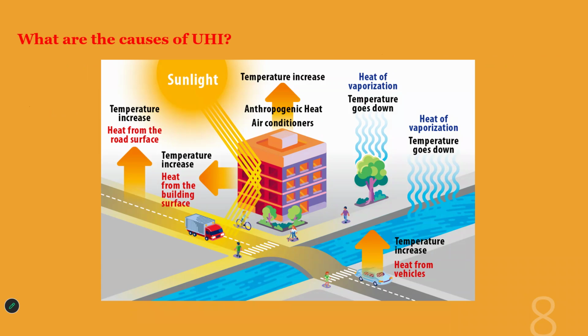Regarding the following research question, what are the causes of urban heat island? I can simply mention that as we noticed, the urban materials like concrete and asphalt absorb and retain more heat than natural surfaces, while reduced vegetation limits cooling through natural moisture release from plants. Additional heat is generated by transportation systems, buildings, industrial activities, and the dense urban layout, which traps heat and restricts airflow.